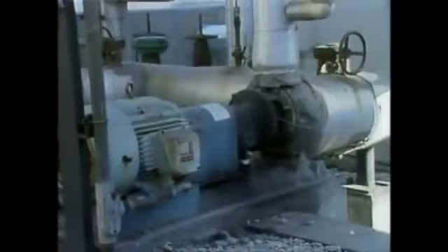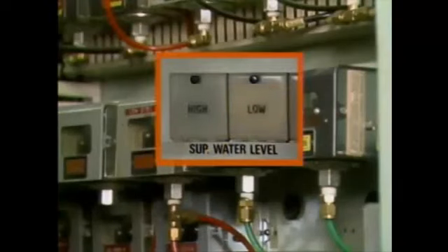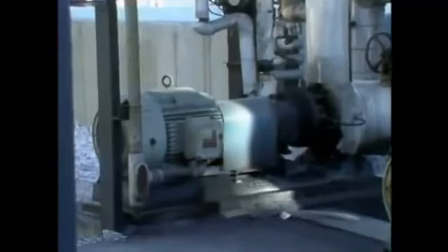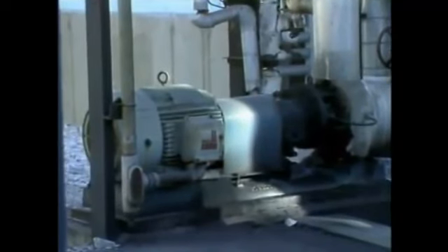For example, if this pump, which supplies water to a holding tank, fails, the water level drops to a point at which a switch activates the low-level alarm and activates a standby pump to help bring the water level in the tank back to set point.